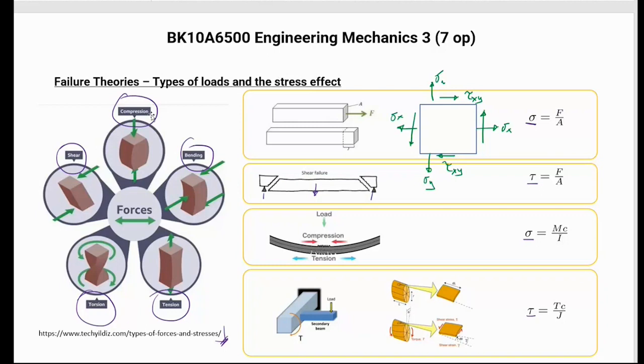Because the idea is to come from forces, loads applied to the part, to the stress tensor, and then from the stress tensor to principal stresses, and then from principal stresses to verification, according to certain criteria called failure theories, of whether the part is going to fail or not. And that's the way to go. You have loads that create stresses that we represent in the stress tensor, then principal stresses, and then failure theory.